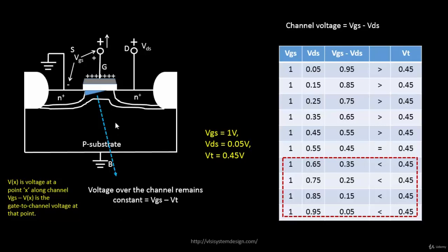In this case, the voltage across the channel remains constant, and that's the good part in the saturation region, because we don't have a dependency on VDS. We do have a dependency on VDS, but not to that extent. I'll come to that point. Basically, this is now your effective channel length, as opposed to the complete effective gate length.